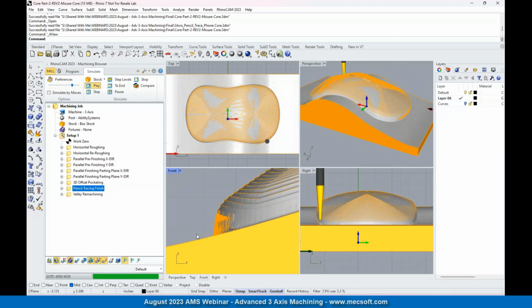And again, depending on how sharp a radius is required or what you can get away with here, you can keep using a smaller ball on the taper mill just to get that as tight as you need to get it. Okay?